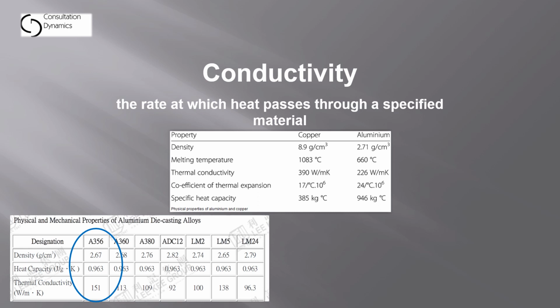The real difference is one is under low pressure, where aluminum is poured into the mold, gravity fed, and the other is high pressure, such as what we typically think of as die casting, where it's forced under extremely high pressure into all kinds of intricate shapes. The A356 material is what classically is used in sand casting and permanent molds. It's a process we use regularly at US Architectural and Sun Valley for the shapes of our lanterns and all of our fixtures. Most importantly, it's used in all of our heat sinks.